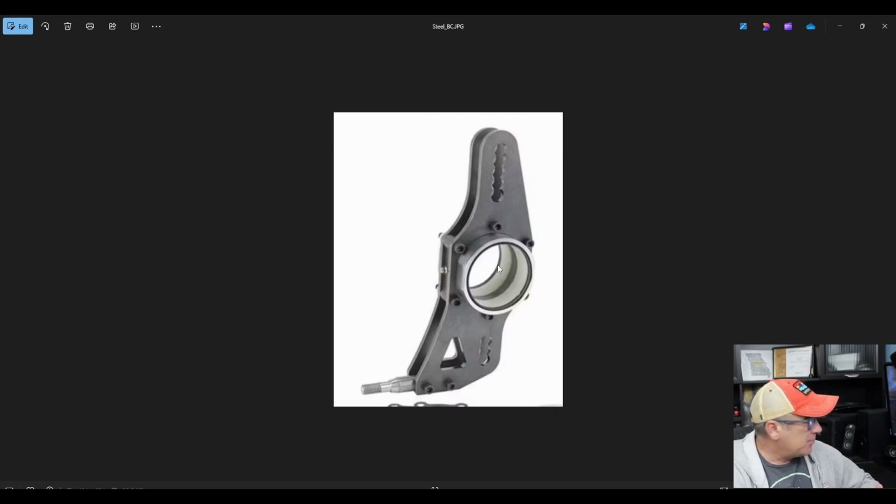But in a dirt late model, we have what are called bird cages. On that side of the bird cage where the axle tube goes through, there's a bearing, and this entire housing is free to rotate on that axle tube. So we call that a decoupled connection point. That is where we get the term live action decoupled rear suspension, because the axle housing is decoupled, or not rigidly connected, to the brackets that the 4-bar links connect to. We have to counteract that rotational force with other means, and in most dirt late models we do that with what's called a fifth arm.